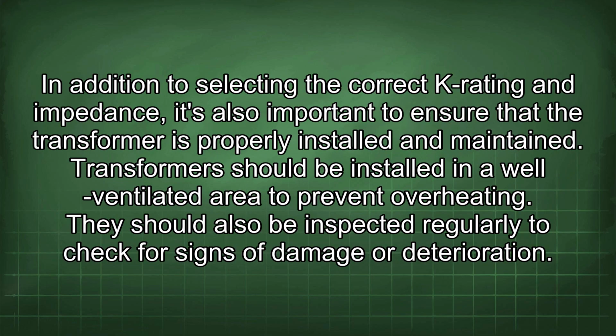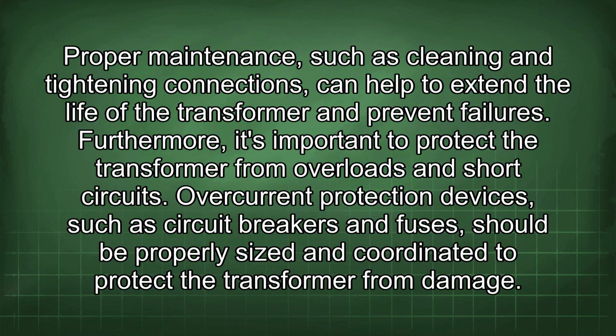In addition to selecting the correct K-rating and impedance, it's also important to ensure that the transformer is properly installed and maintained. Transformers should be installed in a well-ventilated area to prevent overheating. They should also be inspected regularly to check for signs of damage or deterioration. Proper maintenance, such as cleaning and tightening connections, can help to extend the life of the transformer and prevent failures.